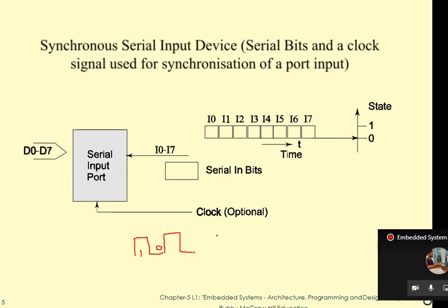Okay. So what is a positive and negative edge trigger? Positive edge is nothing but, here you can see, in this time period it is neither 0 nor 1. So it will be in both conditions. Once it reaches that maximum, after that it reaches, right? So this is called the positive edge, which is going from a 0 to 1 condition. Negative edge triggering is nothing but going from the higher value to the lower value. So this represents the negative edge triggering.